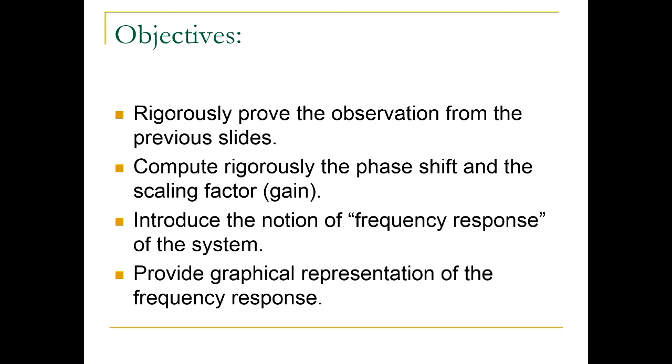And they underlie a lot of the analysis and design techniques we will learn. You will be able to determine stability from frequency response, and you will be able to design robust controllers that tick off some performance specifications in terms of response, damping, overshoot, rise time, but also robustness to disturbances in certain frequency bands.